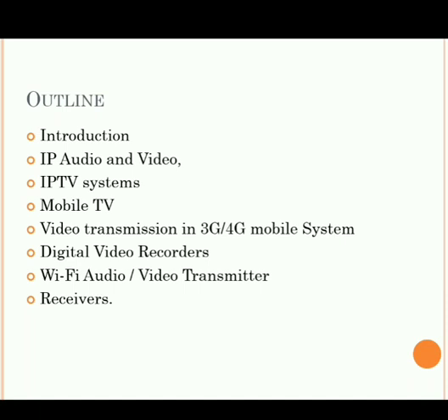Satellite distribution can be included in IPTV network architecture in several ways. The simplest is the IPTV to DTH architecture, in which we are using hybrid DVB broadcast set-top boxes in subscribers' homes. They integrate satellite and IP reception to give near infinite bandwidth with return channel capabilities.